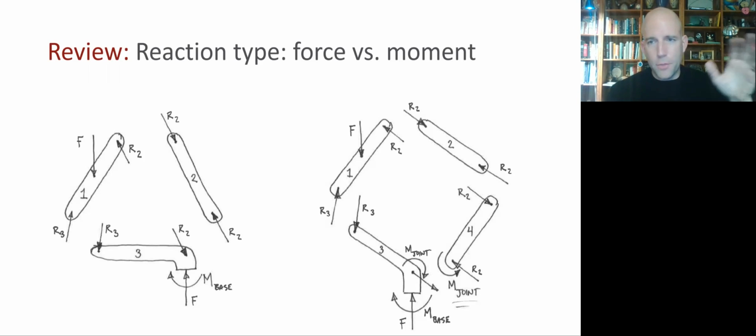We talked about this a little bit in the topic reading when we discussed why triangles are strong. In this triangle shape, if we do our free body diagrams for each link, we can have a scenario where each reaction is just one force. So at each of those joints, you could have two surfaces just pushing on each other, and we wouldn't need the connector hardware to be in tension or be tightened too hard.